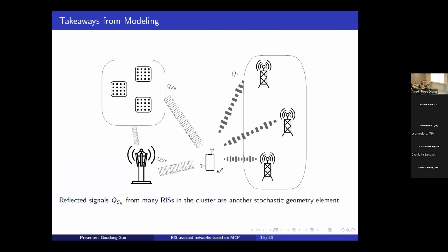What is interesting here is that with the introduction of RIS, you make the computation between signal and interference and noise more complex, more interesting. For SINR, it's a comparison of signal parts with non-signal parts. You can imagine that a signal has to compete with a group of interference and noise. And you probably ask yourself, where's my friend, right?